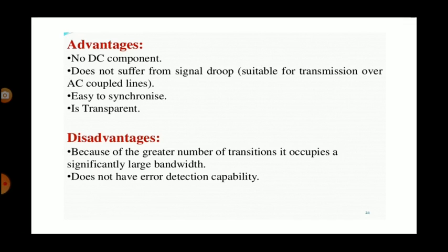Advantages: no DC component, does not suffer from signal droop, easy to synchronize, is transparent. Disadvantages: because of the greater number of transitions it occupies a significantly larger bandwidth, and does not have error detection capability.